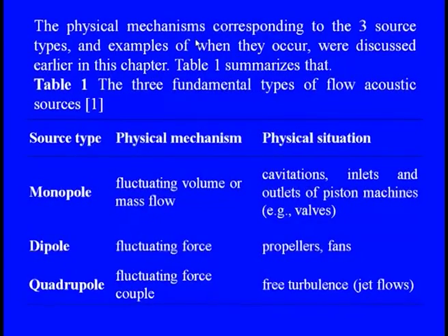And the quadrupole is something in which it is clearly not only the force, but the moment, couple, or any kind of combination. We cannot say that only the force is responsible, but when the force is applied along a line of action, or at a certain distance, it can create a couple, and this couple is also responsible for huge sound or vibration generation.